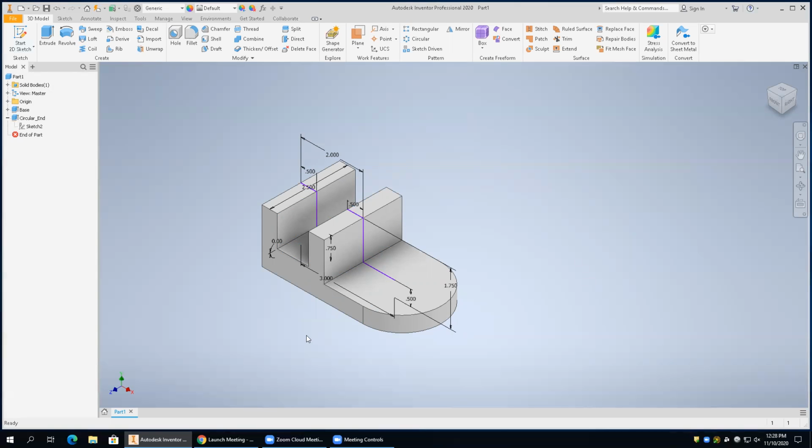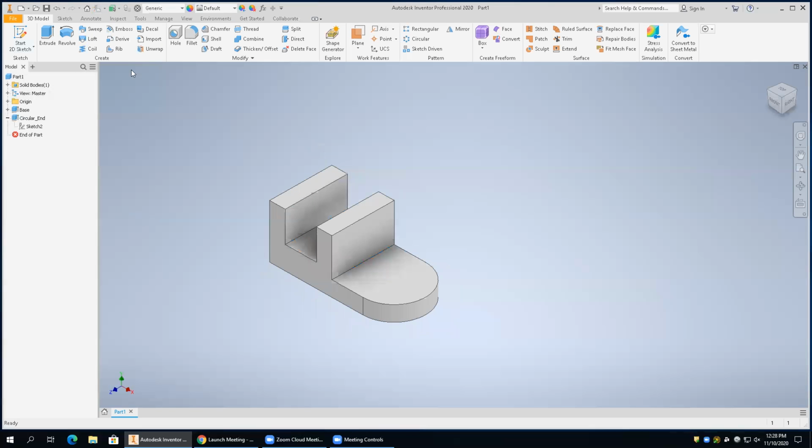We're also going to go to the extrusion, the 2.5 here. We're going to double click on that, and set it from 2.5 to 2. And again, you'll notice the dimension changes, but the part didn't update. In order to make your part update, you have to go up to the top on your quick access toolbar. You see it at the top, it looks like a lightning bolt. That's called a local update. You select local update, and it updated your part. It changed it in both dimensions. And notice the circle went with it because they're locked together.